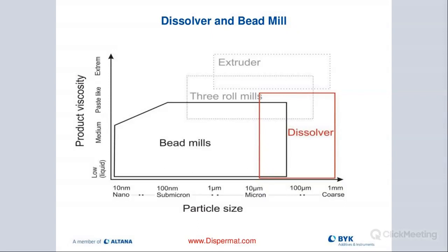And that will help us then to go to much, much smaller particle size, all the way down to sub 50 nanometers with the right type of media. This should not be a problem. But basically, you can see right there is a threshold, and 10 microns is really the limit of how small you can get with the dissolver. And you shouldn't go higher with the bead mill with large particle size because the problem is then you need to switch out the beads. And if your particles are too big, there's always clogging of the screen or the dynamic gap. So it's always good, and important, to first use a dissolver to break these large particles and then go to the milling systems.